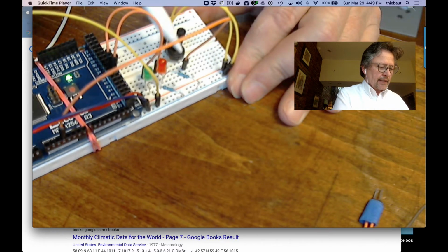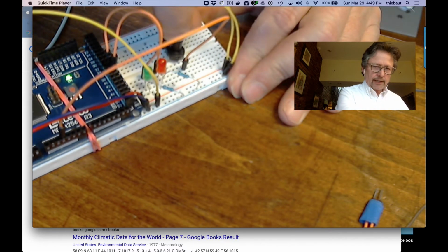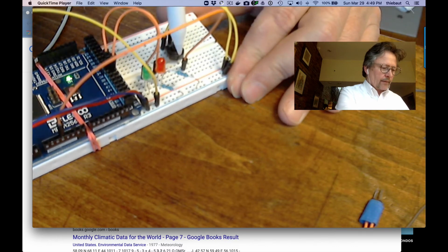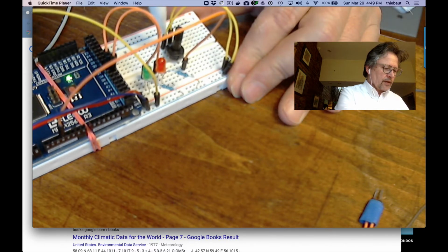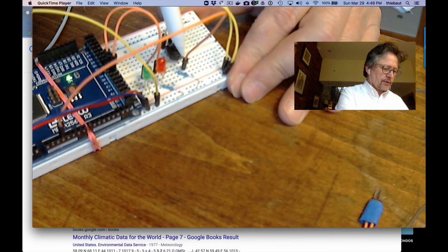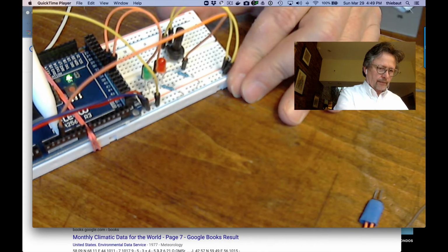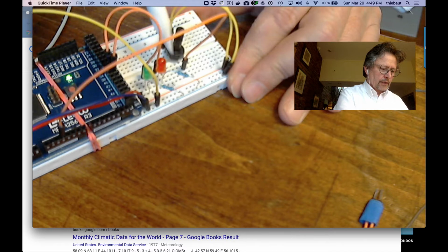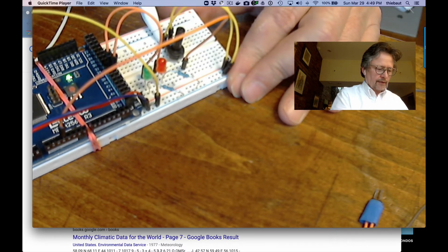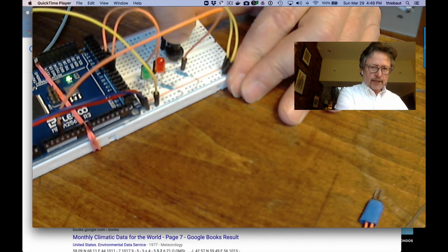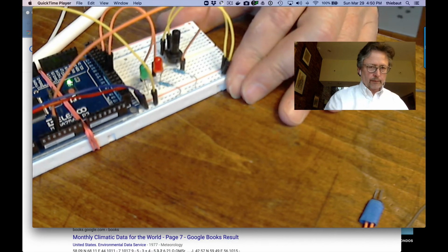Okay, and so that's a resistor, and by turning that little knob at the top, I'm making a little piece of metal go in between. So this is a resistor that is around here, and by turning the knob I'm going to change the resistor. The middle point here will be connected to this orange wire, and that's the one that goes to the analog pin. So the analog goes to the middle, and the other 2 go to +5 and ground. And then by turning this, I should be able to make the numbers change.